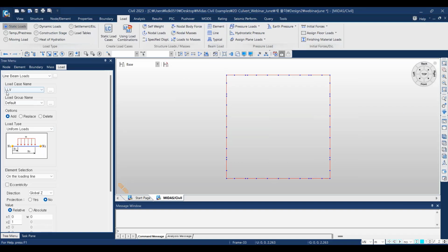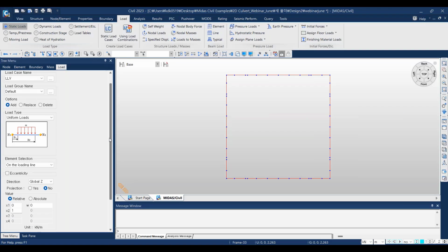element here, and we are going to input first the live load in vertical direction. In vertical direction, the value was 13.5, and the load is uniform. We are going to use the local Z axis as specified for the element local axis. So we are going to select the direction of local axis. Make sure you don't miss this point, it is really important. Selecting the axis matters because of the different pressures we are going to apply on the structure.